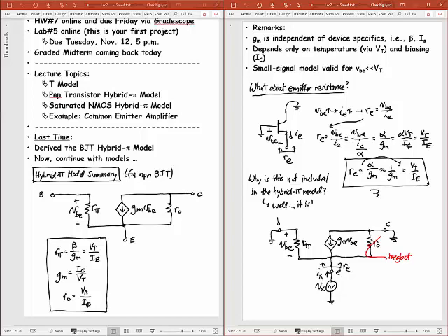When you put the test voltage, usually the voltage would be plus to minus there, and the current direction would be going up into this. But in this case, it's also the same thing as the voltage direction being this way and the current going down, right? And so in that respect, I could say that the resistance seen looking up this way is going to be equal to this voltage VBE divided by this current I sub E, right? Where these are now small signal voltage and small signal current.